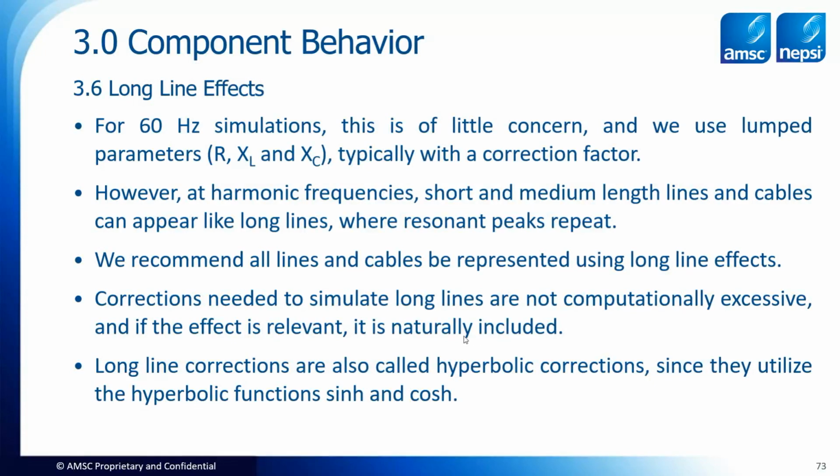However, one of the things to note is that it's not computationally excessive. So if you ever get a software program, and you'll find this to be true, that they're not modeling it, or it's not included by default, there's really no reason for that. Even from the very beginning, when we were performing analyses with matrices 20, 30 years ago, the long line corrections were really not excessive for a harmonic analysis. So why they're excluded, I'm not really certain. But again, I recommend they always be included for your harmonic analysis.